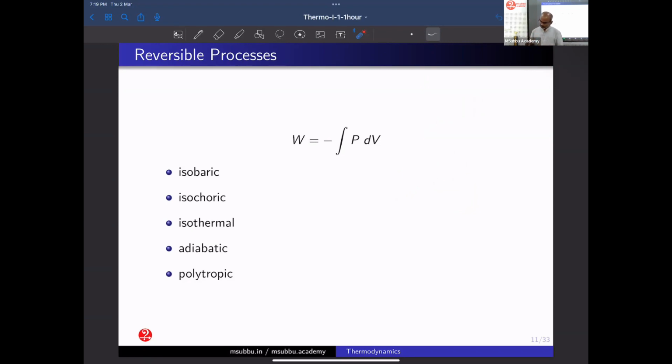Okay, at least in the calculation of work requirement for a closed system, definitely we should see whether the process is reversible or irreversible. So you have to look into it in detail. You can easily get to know by a statement like there is an external pressure. There will be such statements available. Okay, that we'll see with reference to a problem.